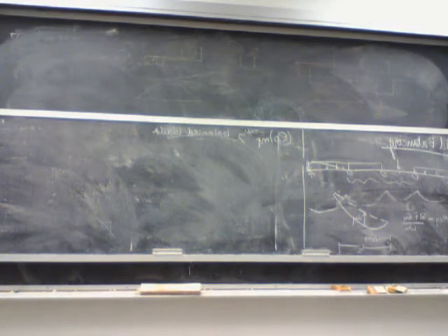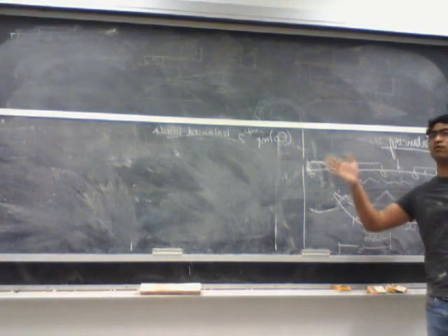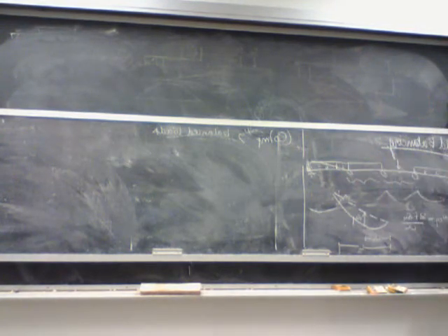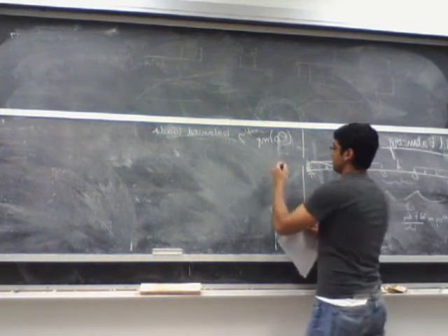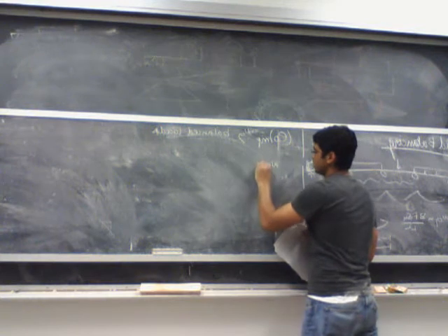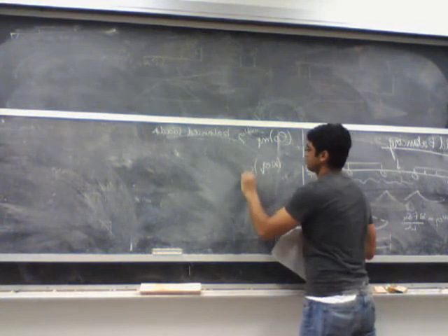Now what you need to do is find one prestressing force which will be the same for all the spans, and the only thing that you can vary within the span is your E naught, because you cannot vary the prestressing force between different spans. Once you fix the prestressing force in one span, it's the same force for all other spans. So you can write omega equivalent in, let's say, span 1.